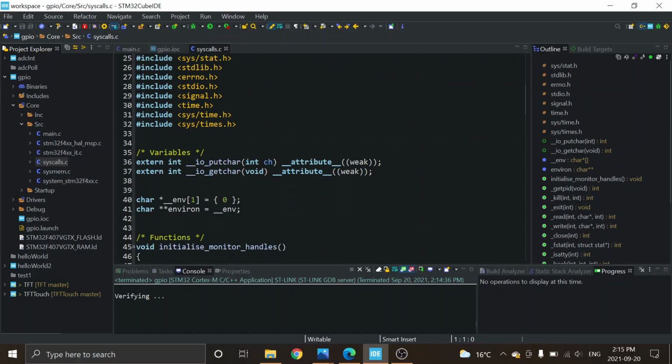it says put character is external, and it's defined as weak. In other words, I defined a placeholder. If you want to use it, you need to define it. They just said we're going to have IO write call put character. I don't know what it is. So what you do is you take put character here and you put it somewhere.